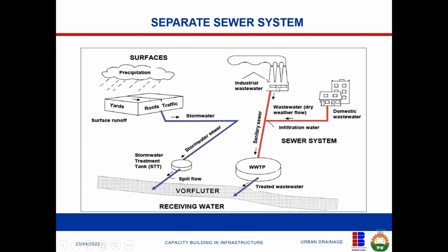So that is why this sanitary sewer must be treated in the treatment plant for some few days, maybe 10 days, 15 days, by injecting oxygen. Some oxidation, you know, when I say the BOD, biological oxygen demand, is 400, what it means is that you need 400 milligrams of oxygen per liter to treat 1 liter of that wastewater. So you bring it to a manageable level, okay? A level where it will not cause harm, first to the aquatic organisms, and then maybe to humans who are living downstream and need it.